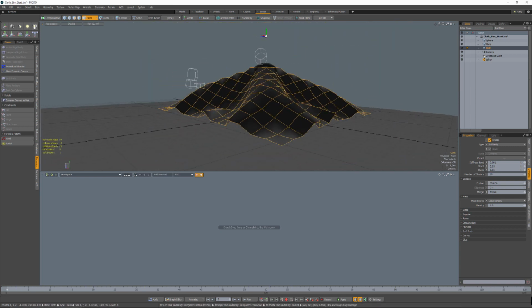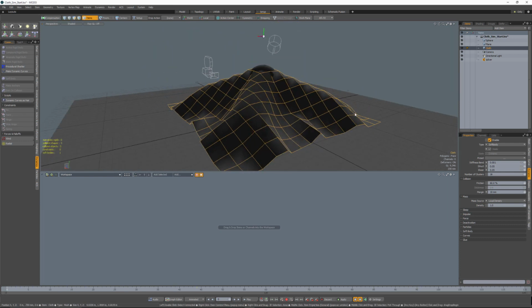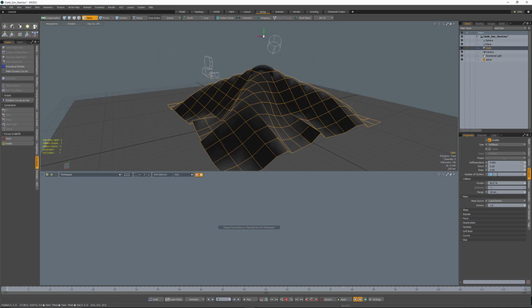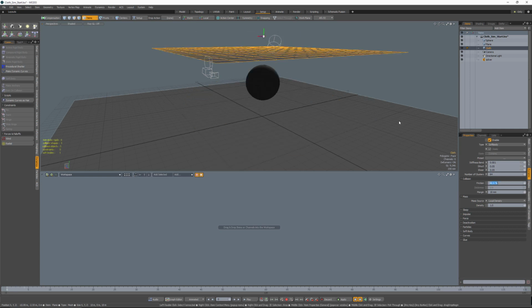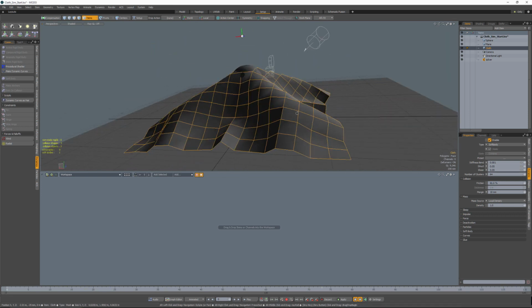You can see we start to get a little bit more collapsing of this, but now we're actually hitting up to the resolution limit, both of our current mesh and for the number of clusters. So I'm going to increase the number of clusters here. Let's start just by going up to 64, and we should see a little bit of improvement here. Yeah, a little bit. We see a little bit more noise and softness through there.